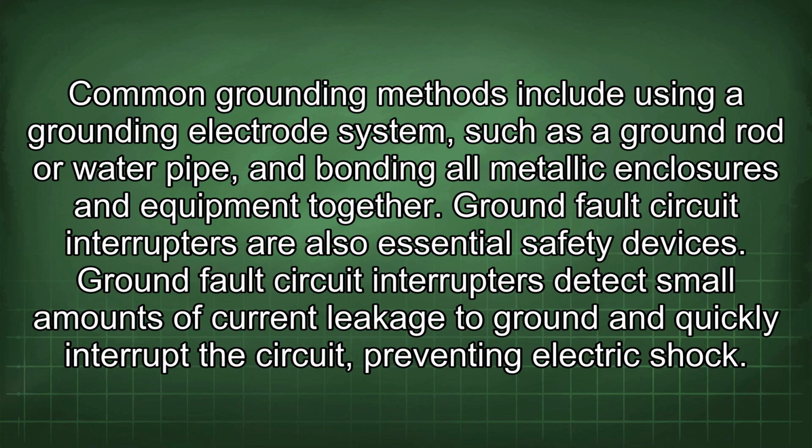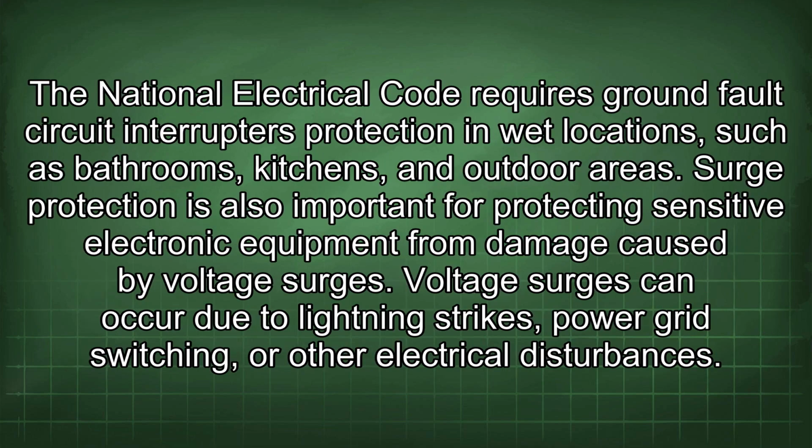Ground fault circuit interrupters are also essential safety devices. Ground fault circuit interrupters detect small amounts of current leakage to ground and quickly interrupt the circuit, preventing electric shock. The National Electrical Code requires ground fault circuit interrupter protection in wet locations such as bathrooms, kitchens, and outdoor areas.